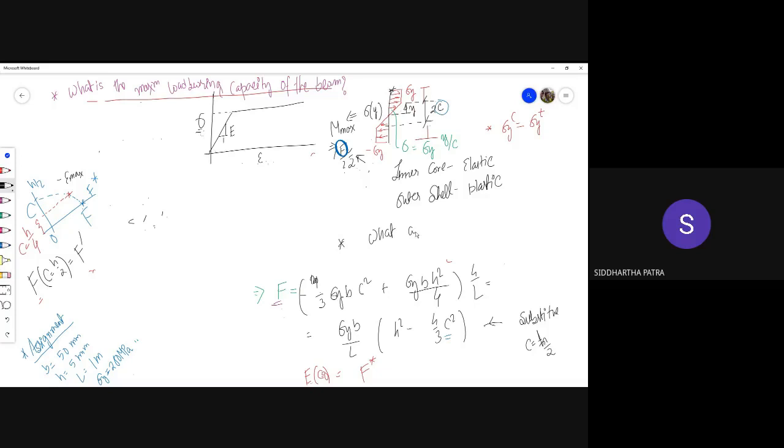what are the residual stresses? So the thing is, let's say with yielding you have reached somewhere over here. Okay. And now you start unloading. And as you might recall, the unloading window is the elastic window of unloading happens elastically, and that window extends to twice sigma y,